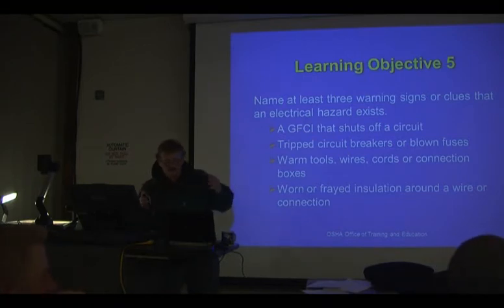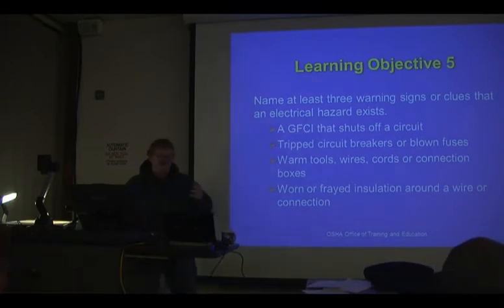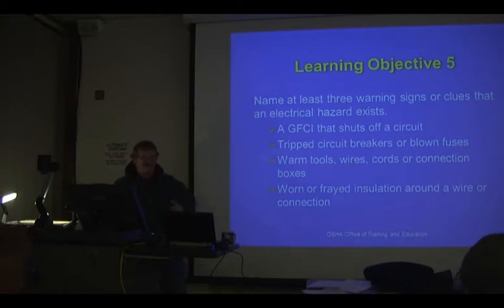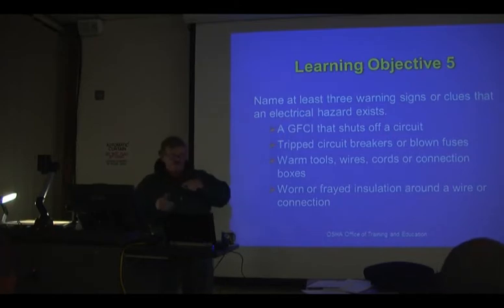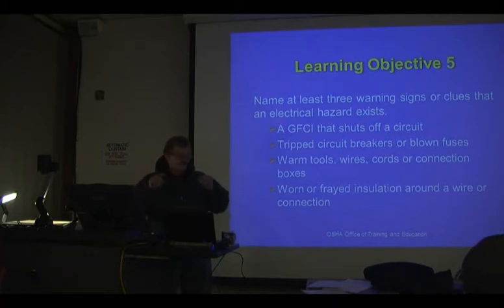So your drills and your hand saws and stuff, or your electric saws, are the same way. Everybody's seen that thing pull out. Okay, you've all made connections where you wire something and you crimp a terminal on there and you see about 1/8 of an inch of bare wire. Well, that 1/8 of an inch of bare wire shouldn't be there. Those terminals have that outer case that you crimp on there so you don't hit that wire.